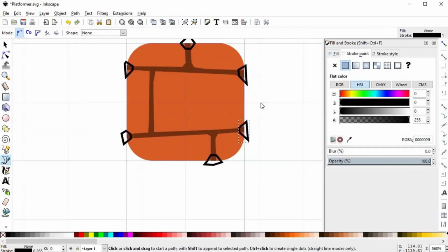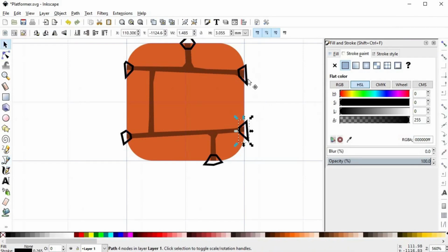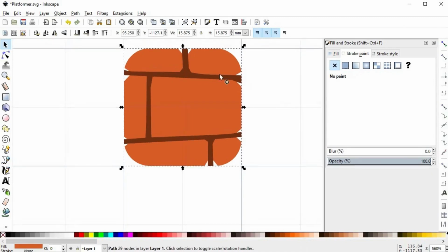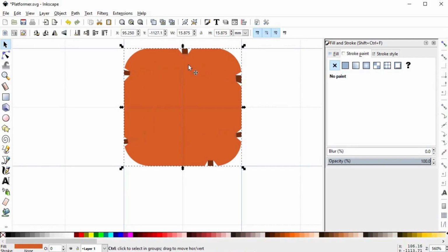Now, so you don't have to go one by one making 6 different operations, there is a nice little trick you can do. You can select all these shapes and join them into a single shape by using a union. And yes, unions work with shapes that are not intersecting. Now you have a single shape and you only have to do a single difference operation. And now the mortar joints need to be adjusted to this new block silhouette. So I'm sure you know what to do. Perform an intersection with the block.